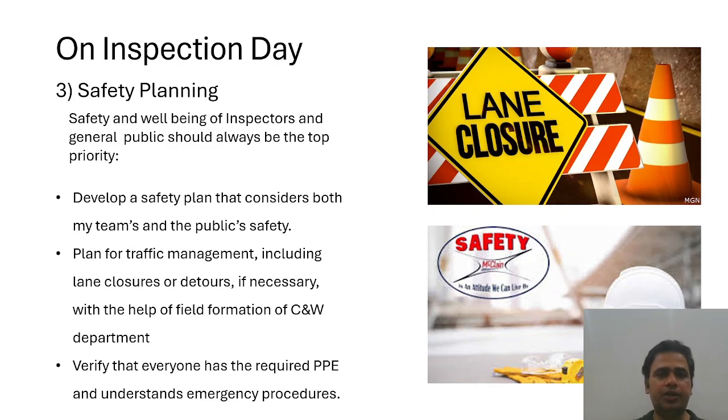This is very important. You need to ensure that you have a proper safety plan. You have the relevant staff with you if required, and you should carry safety cones in your vehicle for the lane closure. And there should be no compromise on safety. Many times under the bridge, there are challenging conditions. There is usually construction debris under the bridge, or maybe a river or a stream is passing, or there could be other hazards under the bridge. So you should ensure that you have all the safety equipment with you.